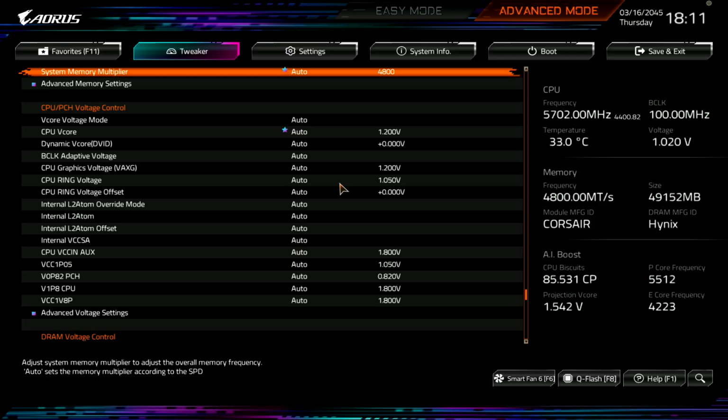My suspicion is that basically all of the degradation is due to Intel's stupid vdroop compensation, and it's not anything to do with power limits or current limits or anything like that. It's just the fact that the CPU sometimes sends VID requests for 1.6 volts, and then it gets 1.6 volts. Seems like a kind of dumb thing to do, but anyway, I don't know that for sure.